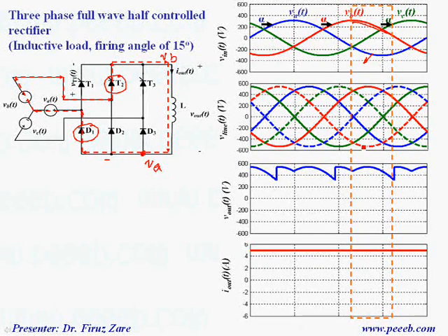That means over that cycle we have phase B minus phase A, which is another line voltage. That means we can get different voltage waveforms by controlling the firing angle of this set of thyristors, whereas this set of diodes cannot control that terminal's voltage.